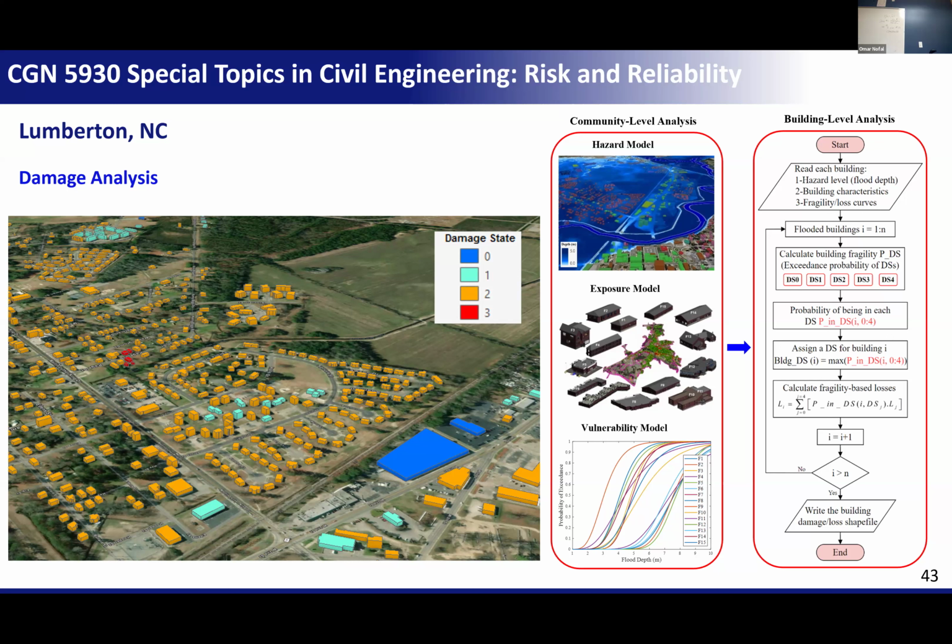You don't plug the water 100%, you keep it flowing. Let's say we have a dam blocking the whole water, but if the water reaches a specific level, it's going to be dangerous to the dam and the dam is going to fail. So you let the water flow at a specific rate that doesn't damage the dam and also doesn't cause flooding downstream. However, sometimes extreme events are beyond the dam capacity. For example, the dam is built for a 1,000-year event, but if you get a 2,000 or a 10,000-year event, there's no way that you can handle this. So dams are still structures, and we call these control structures.